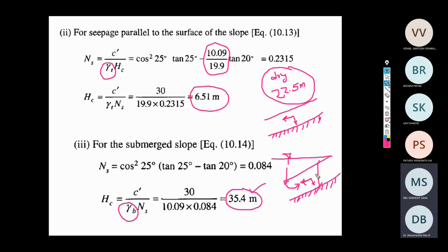Okay, or else just recall your soil nailing. When you do the soil nailing, where do you do it? Everyone, have you seen any kind of soil nailing technique? Yes, sir. We can also relate it this way. Due to submerged conditions, weight will increase, which results in an increase in normal stress, and finally an increase in the shear strength, sir, like s equal to c dash plus sigma tan phi. No, they will not increase any kind of strength. Don't relate it to strength because these are purely external mechanisms, some kind of overburden.